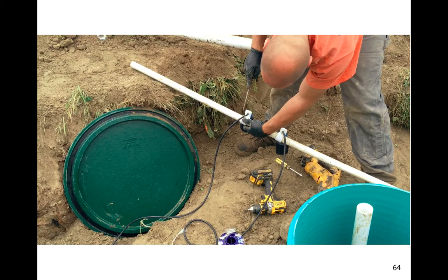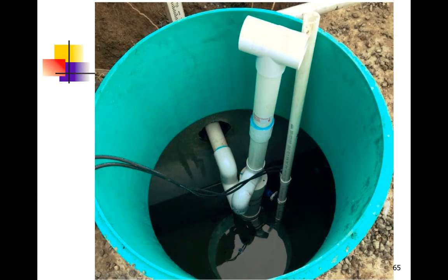So here you have the floats accurately installed, and you haven't had to do any measuring or calculating whatsoever. The only thing you can do at this point to screw it up is to put the float tree in upside down, but it's very easy to check. Put the float tree in the tank. As long as the top float is at the same elevation as the top of the 4-inch splitter valve, and the bottom float is 8 inches below that or so, you've done it correctly.